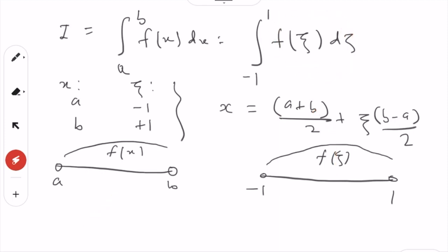If you don't have a rectangle or square, you can have an isoparametric element, where x and y for any irregular shape can be reshaped as xi1 and xi2, mapping from an irregular shape to a square shape.